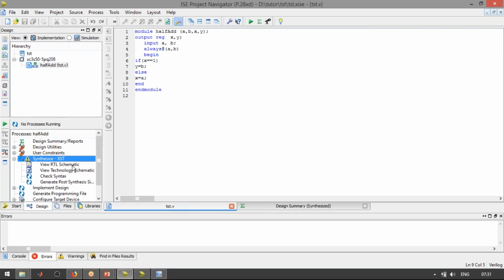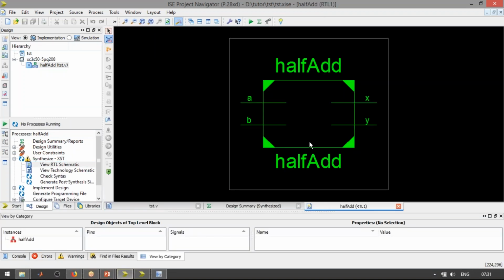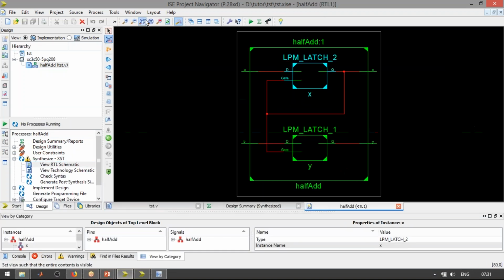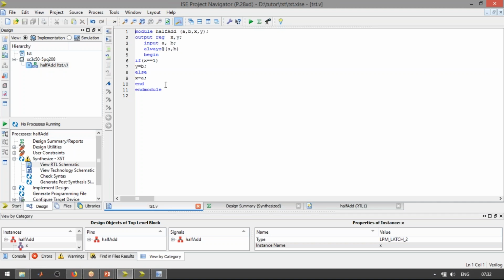So after synthesizing, it will form the latch. So like this, we are defining the module. The only case you have to understand: if it is an always statement, that variable becomes a register that forms a memory element. And in the case of the assign statement, it is a concurrent statement. So for the assign statement, we are not using that register. For example, you may see the same example.